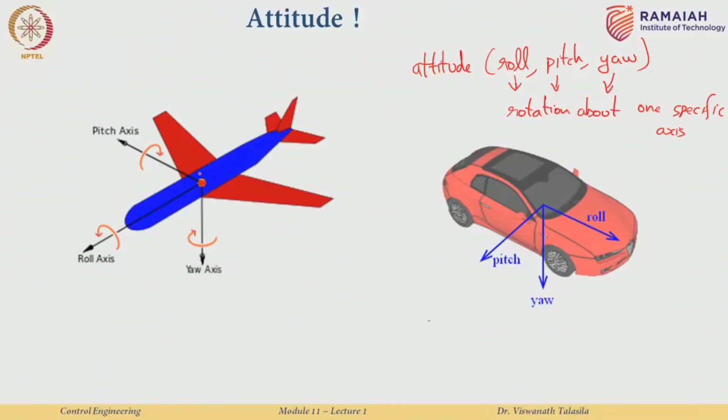You mount your sensor, the gyroscope, at this place, and this is the forward axis, this is the vertical down axis as it is called, and this is the right axis which completes the orthogonal axis system.